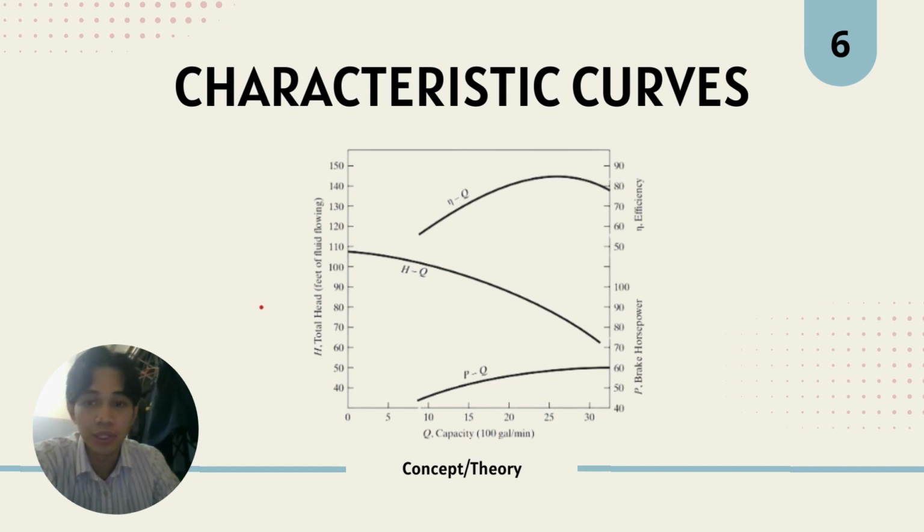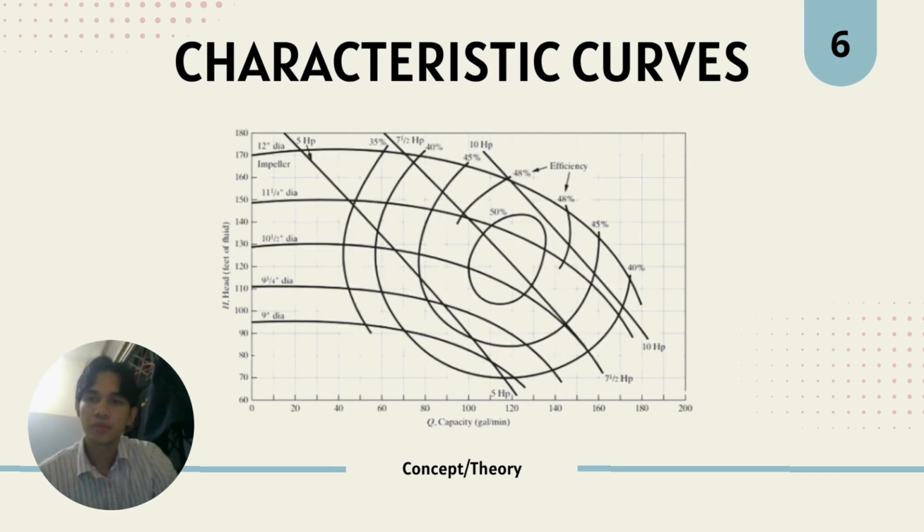The pump will only operate at certain points on the characteristic curves. For a particular pumping task, the required head and volumetric flow rate point must lie somewhat below the characteristic curves, as seen. Now we'll be talking about another characteristic curve, whereby the characteristic curve moves upwards with increasing impeller diameter.